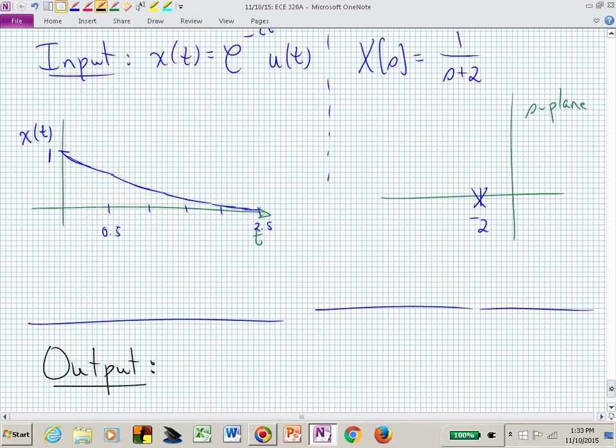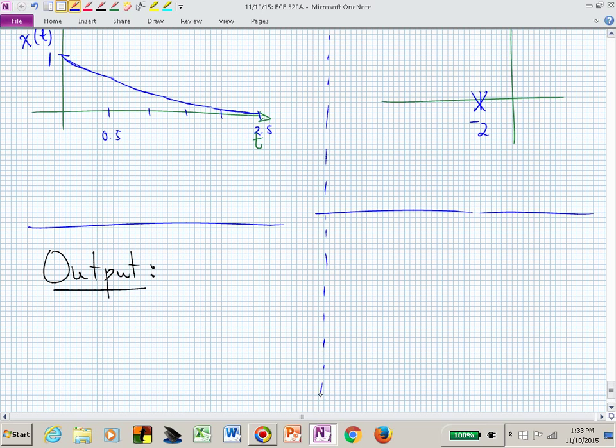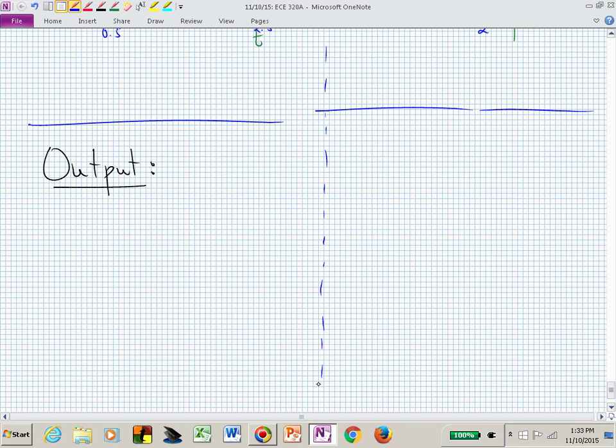Well, here's where you probably want to play in the frequency domain. You go, I've had enough of homework 7, let me do some algebra in the S domain, let me just find the output Y of S. What's that equal to if I have a system and an input and I know both of their transforms? Multiplication in the frequency domain. And what does this pole zero diagram look like now for this particular choice of X and H?